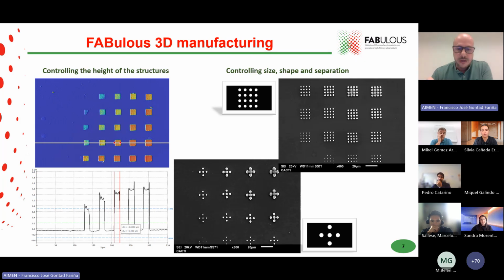Instead of going to the fabrication one element by one, we use advanced parallelization techniques like spatial light modulators to tackle the fabrication of several meta-atoms at the same time. For example, in these scanning electron microscope images, we are projecting 16 spots all at the same time. And by changing the processing parameters, we can observe how we can produce these small cylinders with different diameters.